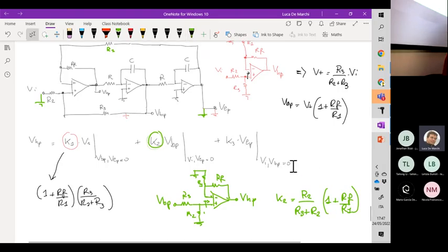So this is the green circuit. Let's compute the last one, the orange, which is related to the combination in which the low-pass filter is the unique active terminal, while VI and V bandpass are equal to 0.